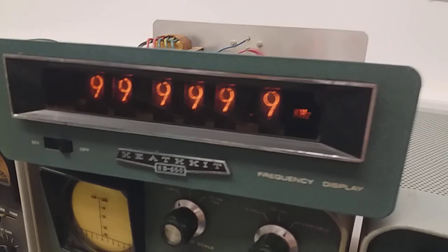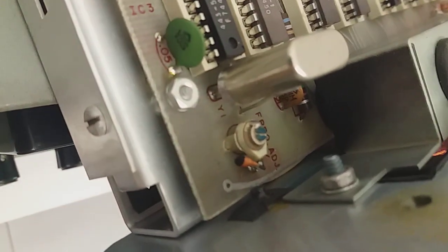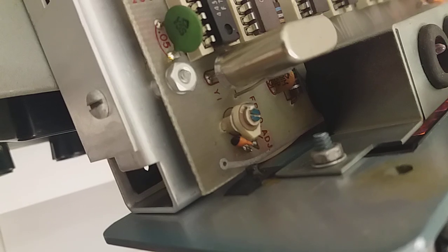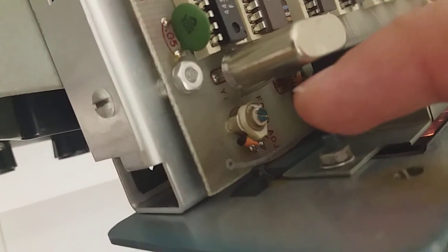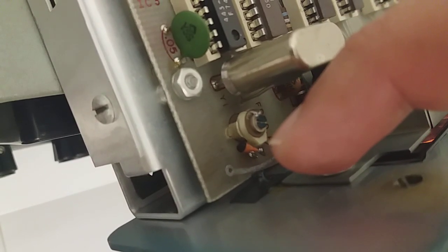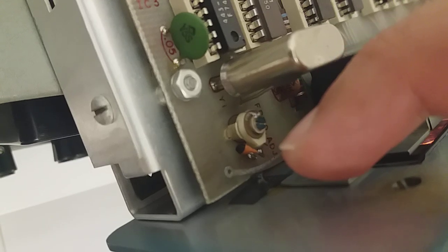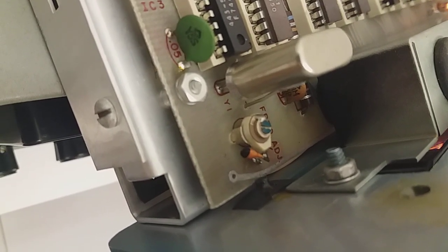And what I actually did was, the trimmer was not behaving correctly here, so I've changed, let's focus a little bit better, I've changed this trimmer to a fixed capacitor of 8.2 picofarads. So actually now we have this main trimmer, the original trimmer, connected in series with a fixed capacitor of 8.2 picofarads. And